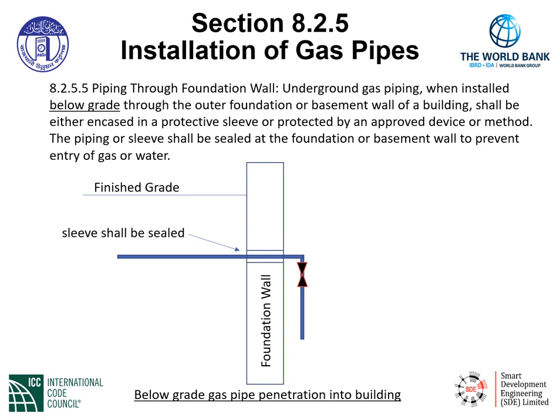The graphic below shows a gas pipe penetrating through the foundation wall below finished grade. As such, complying with this section, we have a sleeve that has been installed in the foundation wall that provides suitable load transfer around that pipe to prevent damage, and it must be sealed accordingly.